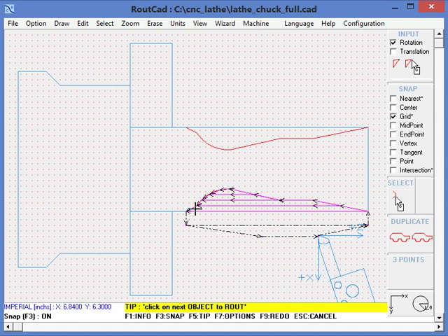But this is just an example. We don't necessarily need to bring it back to where it started from. Sometimes at the end we could move it further away just to give us some room to work and put in a new workpiece, and then when the machining starts again, the CNC will move back to that location and keep on machining.